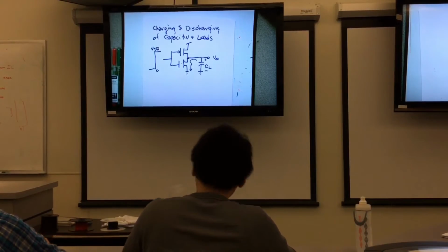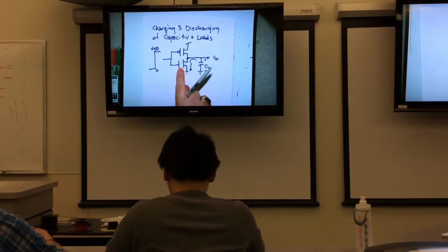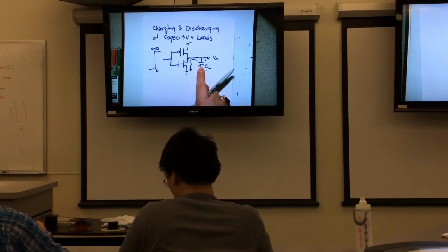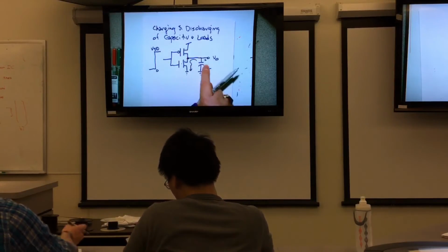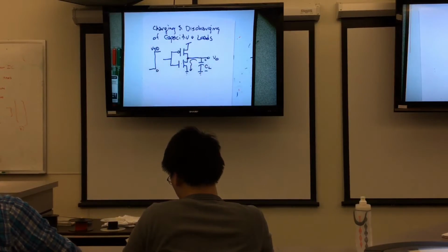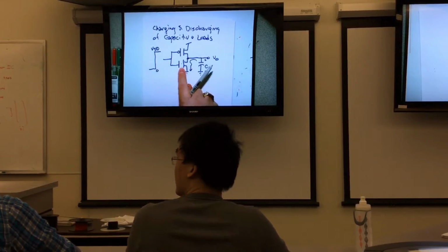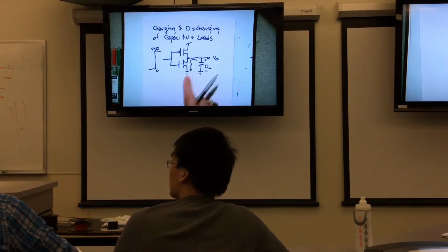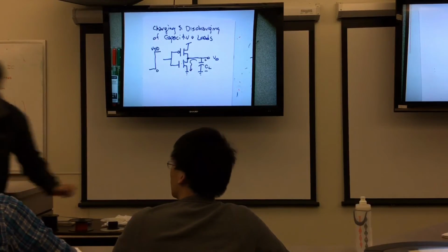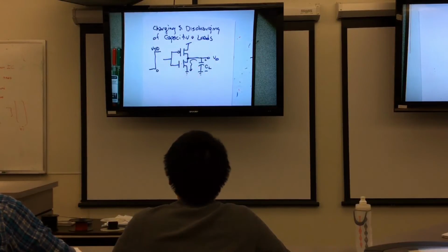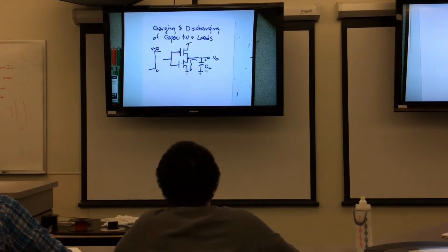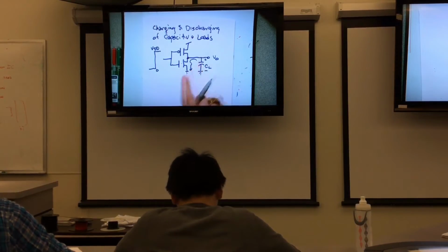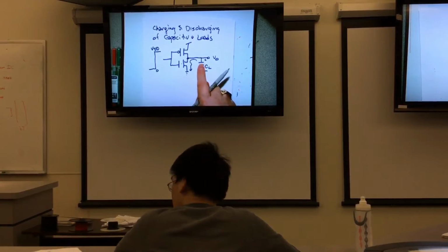You can see it already, even though the heat's coming out of this device, this is the device that's determining the heat dissipation. Because once you fully charge it, that's the amount of energy that's there, and it's all going to be dissipated as heat in the resistor. So we're never actually doing anything with the resistors where we compute heat for CMOS. It's all about this guy over here. Believe me, there's a lot of experts trying to figure out how to get that down.